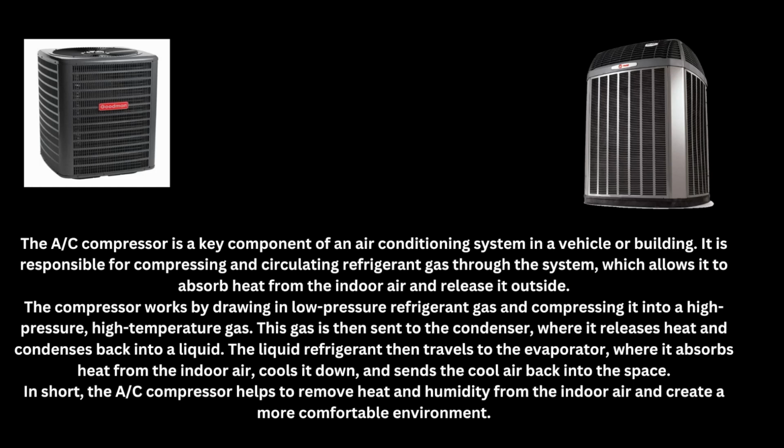The compressor works by drawing in low pressure refrigerant gas and compressing it into a high pressure gas. So basically, as it's coming back from the evaporator after absorbing the heat, it's a low pressure gas. When the compressor gets a hold of it, it pumps it at a hard rate.